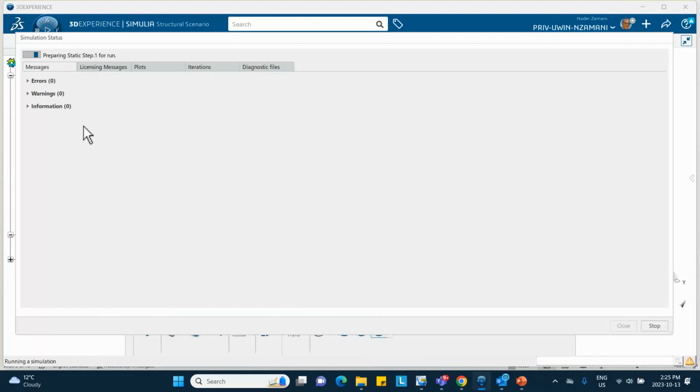There's going to be two increments, the initial increment and then the actual run. Uncheck the nonlinearity, therefore it's not going to be taking it in too many increments. It just does it in two shots basically, or one shot. Okay, done.